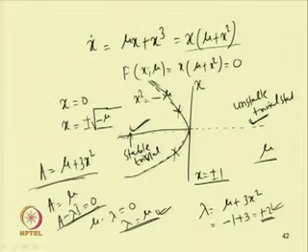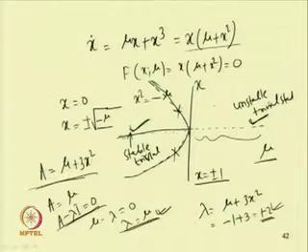So at this bifurcation point, what we have observed is a stable trivial state along with 2 unstable non-trivial states, and after the bifurcation this branch becomes unstable. As there is no solution after this, there will be a catastrophic failure of the system, and this type of bifurcation is known as a subcritical pitchfork bifurcation point.